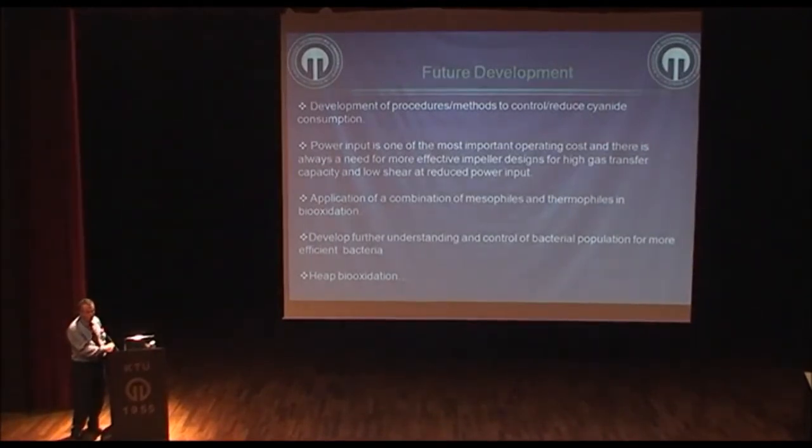So in recent years, more effective mixing systems like hydrofoil impellers, in particular axial impellers, have been developed to improve the gas transfer, oxygen transfer to the system, as well as to reduce the power input of these impellers.